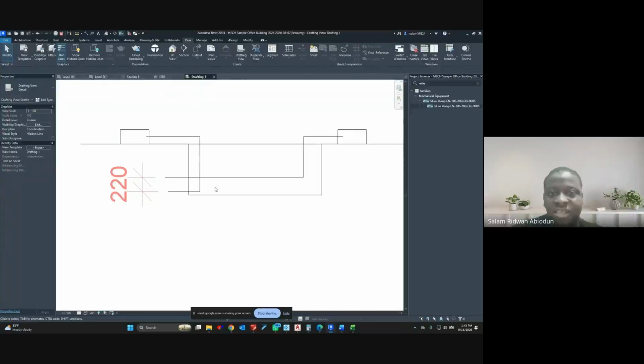Let me just give us an example. Let's say the water for firefighting requirement for this simulation is 20 cubic meters. Then the water supply for the residents, the domestic usage, is, let's say, 15 cubic meters. When you add the two together, it's going to give you what? 15 and 20, that will be 35.